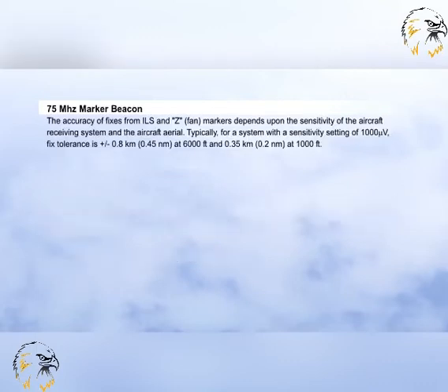The tolerances we have shown you earlier determine the overall fix tolerances for any given type of facility, and it is the variations that are used to narrow or widen instrument approach areas as an aeroplane flies to and from a facility. The area is of standard width of 2 nautical miles for a VOR and 2.5 nautical miles for an NDB at the facility. The optimum and maximum distances for locating the FAF relative to the threshold are 5 nautical miles and 10 nautical miles respectively.